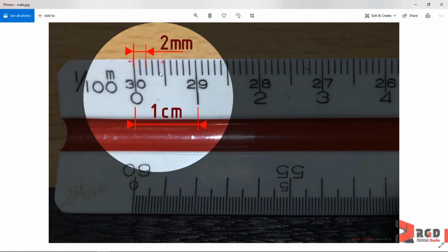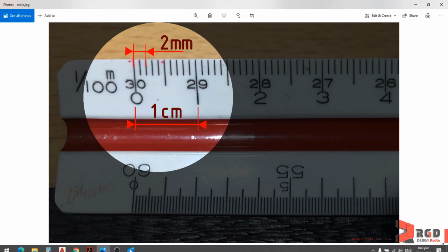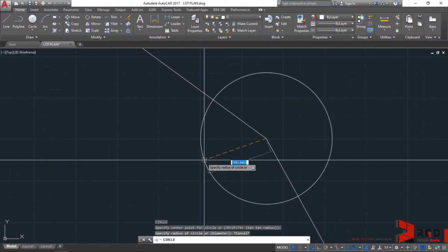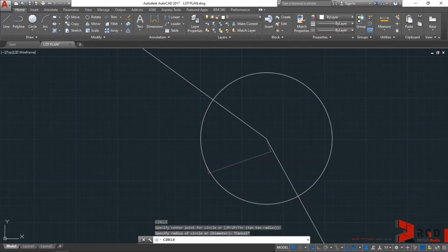And for our circle radius, we want the diameter to be printed. If it's printed in scale 1:100, let's say for example it must be 3 mm. Therefore, we shall input 300 for the diameter, and since we are being prompted for the radius, let's input 150. So going back to AutoCAD, so for the radius, let's type 150, then enter.